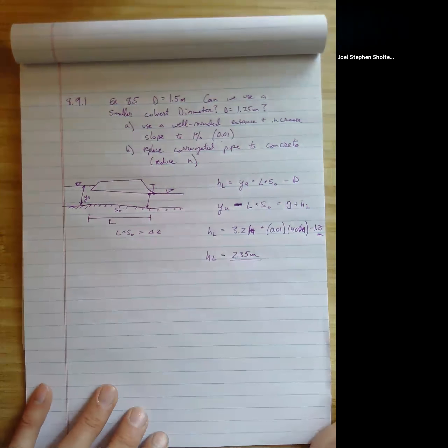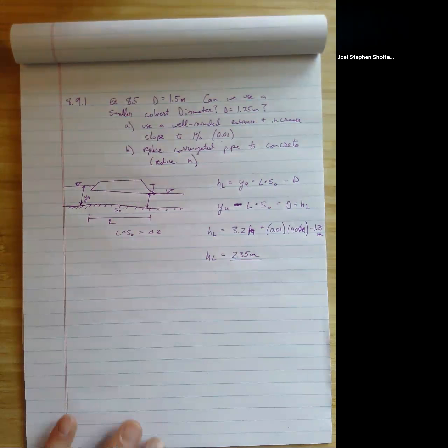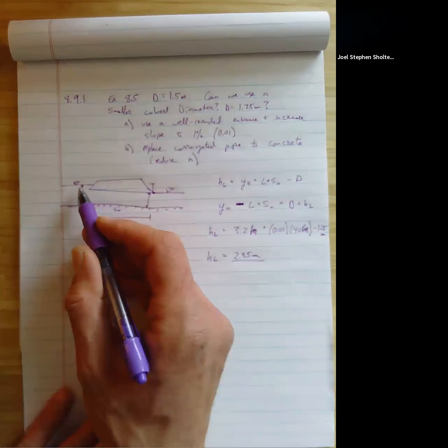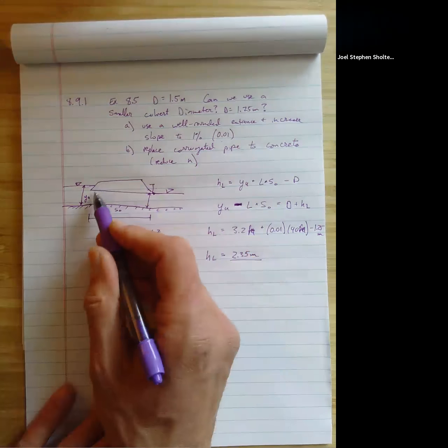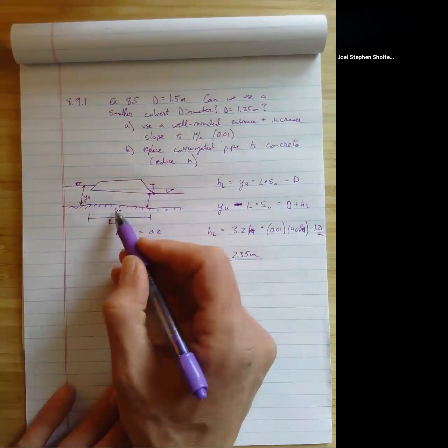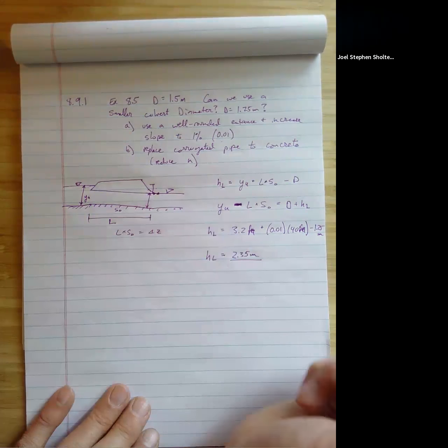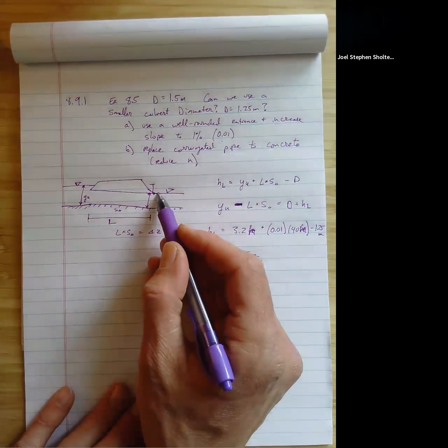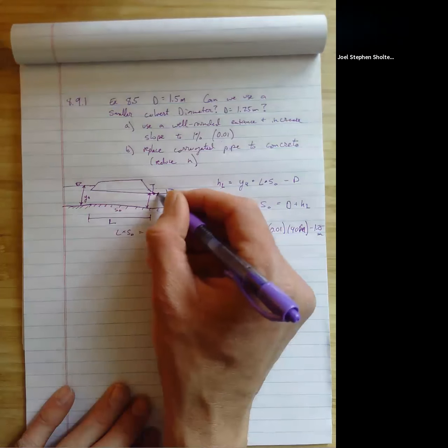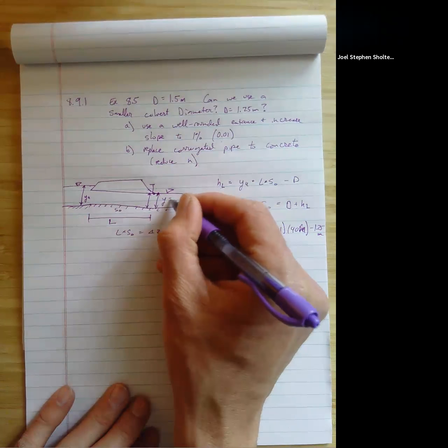And that's literally just saying, well, we had, from before, we figured out that we had a submerged flow up here. The flow moves through the culvert, it drops by the length times the slope, and then whatever energy is available is going to be related to that diameter of the pipe. So the Y is equal to the diameter, right?